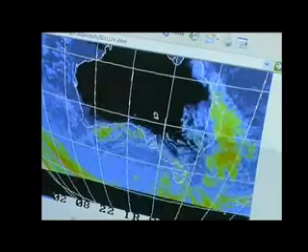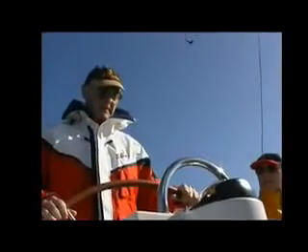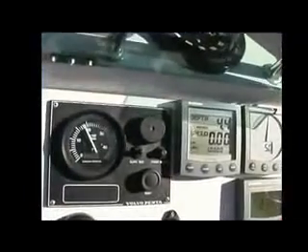When the forecast refers to the significant wave height, remember that some waves may be up to twice the significant wave height stated, and wind speeds can be up to 40% stronger than the maximum given. When at sea, listen to weather forecasts on the public or marine radio. Keep your eye on the sky. Beware of rapidly darkening or lowering cloud. Squalls may not be far away. Head for shelter or for home.